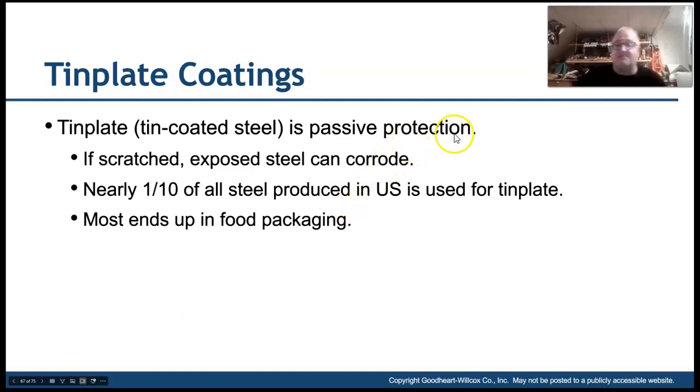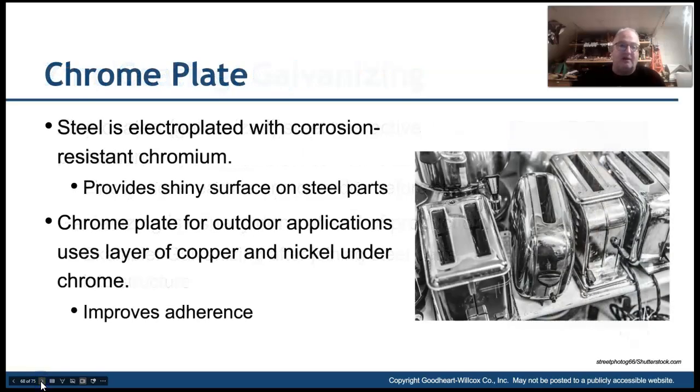A couple of other types of passive protection coatings are things such as anodizing. That typically happens on aluminum, where it's kind of a colored coating that helps to protect it. We also have black oxiding with different types of steel parts, oftentimes in the machine tool industry, on your tool holders and your clamps and other components. That's just a passive protection to help protect against rust as well. It's a form of rust inhibitor too.